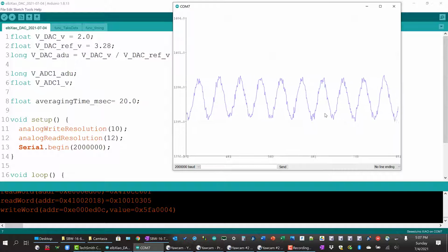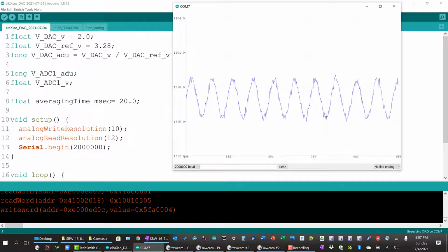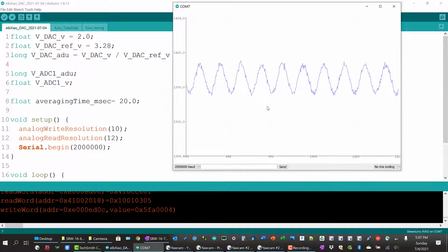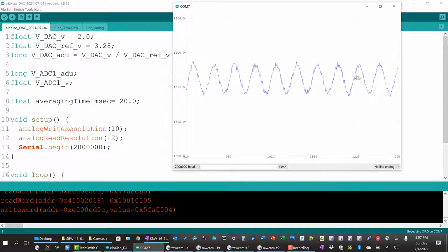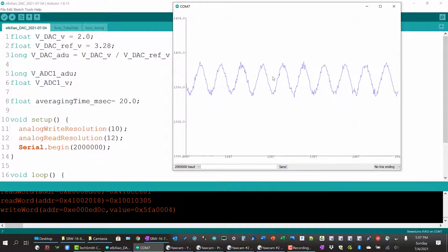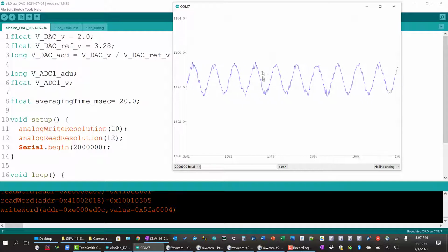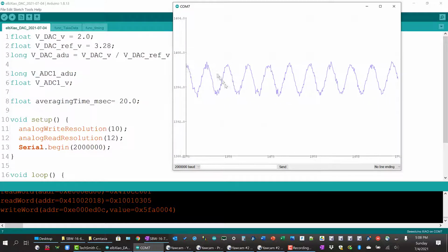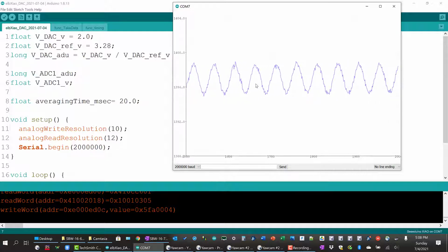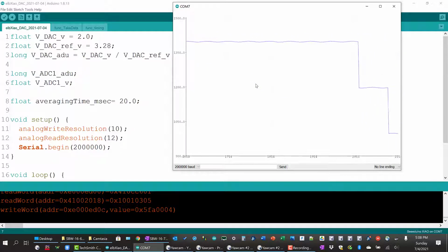It's a great way of monitoring what we've got. We don't want to use a delay statement to control the horizontal scale. We want to use an averaging statement to control the horizontal scale. That way we're not throwing data away, and we're getting a chance to see what that data looks like. The more averaging we do, we can decrease the noise as well, and you can kind of see that here. And of course, if I change the offset a little bit, it auto scales. In the next video we'll talk about how to maintain the scales automatically.